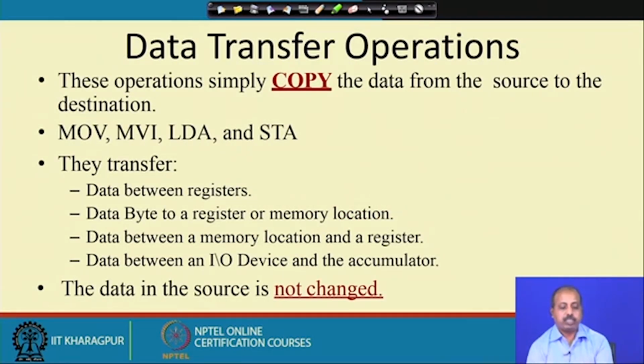The first group of instructions is the data transfer operation. You want to copy the data from source to the destination. Instructions like MOV, which is shorthand for move, then MVI, move immediate, then LDA, which is load accumulator, and STA, which is store accumulator.